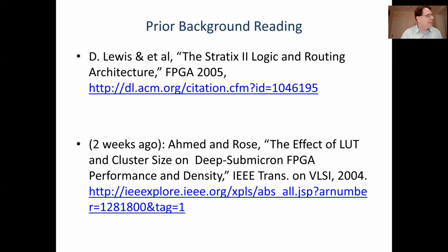Yeah, and Gil has a good point. If you wind up with only input registers and no other registers anywhere, then Quartus will not properly timing analyze your design. It will basically say this runs incredibly fast because there are no paths between registers. So we definitely don't want to get that. If you find your designs running unbelievably fast, like a gigahertz or so, even though you haven't optimized it that much, that usually indicates you don't have any output registers.